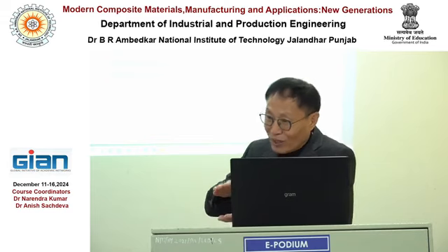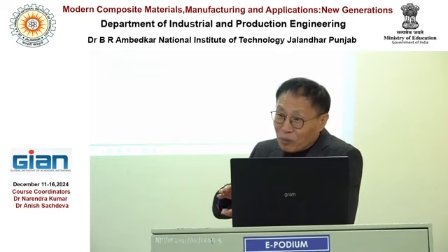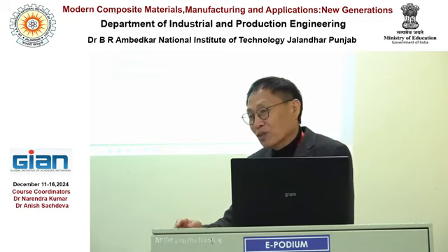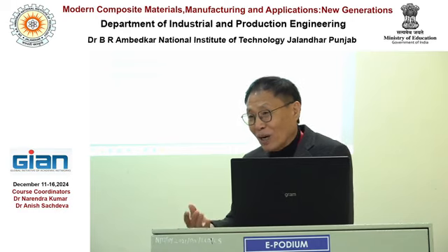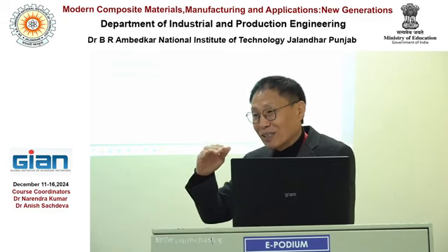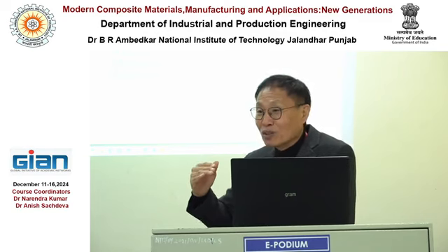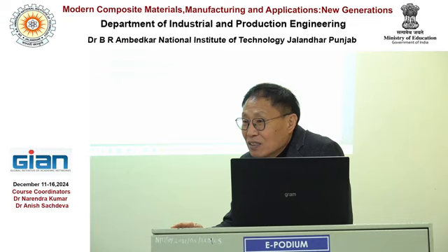Because it must be well compacted, and the resin should be well molten, so that all of the fiber is completely wet. But with VARTM or hand layup, it is not possible. It has a limitation. But if it is through an automated machine, you can control every parameter very precisely.